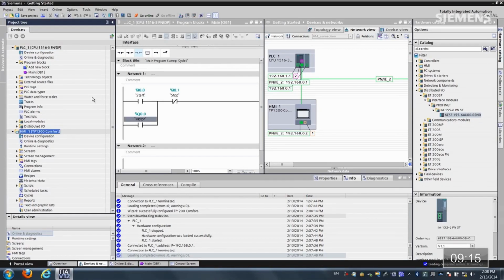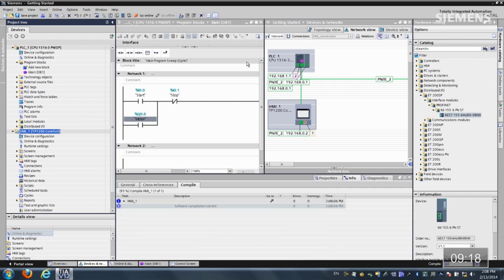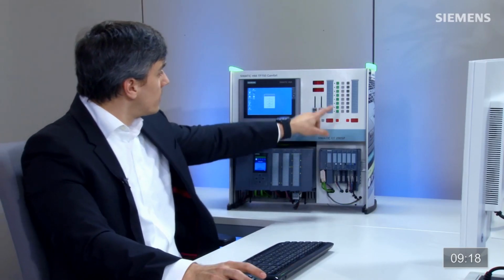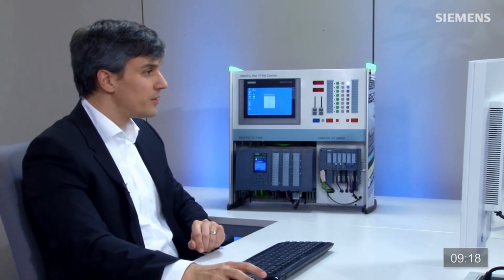At this point, what I like to do is a virtualization of this panel. I have the ability to virtualize any panel in our architecture. That way I can prove it out in a system test to make certain it works the way I want to before I buy the panel. Let's give focus to the HMI. Let's click on Start Virtualization. It's going to make a connection to the actual controller at this point. It has established one. So I should be able to come over here and actually click on our control code. And as you can see on the virtualized panel, it has gone high. It's gone from a 0 to a 1. I was able to build this entire system up in just a matter of minutes. Now that's engineering efficiency.